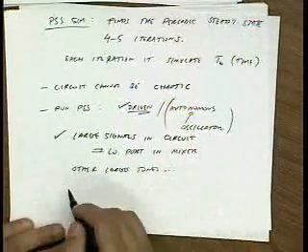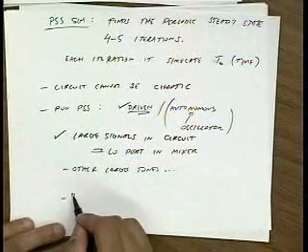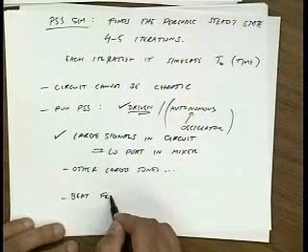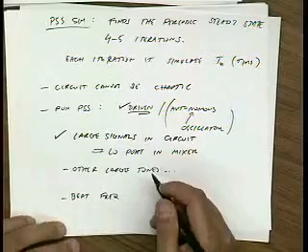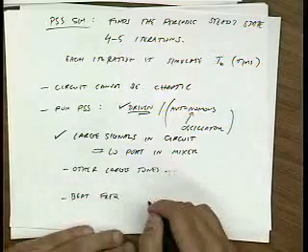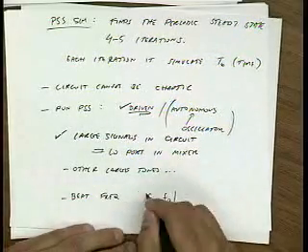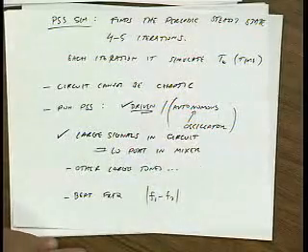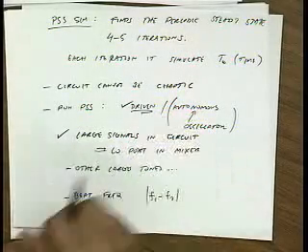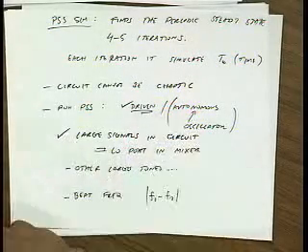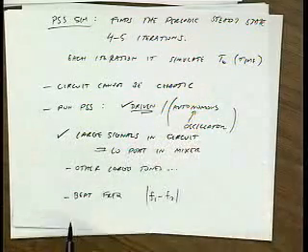Finally, you need to give the beat frequency. So for instance, if you have 2 large tones, it would just be F1 minus F2, right? But actually Spectre can calculate what the beat frequency is automatically if you give it more tones.